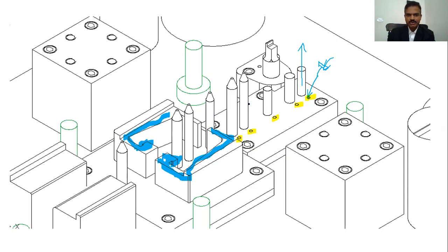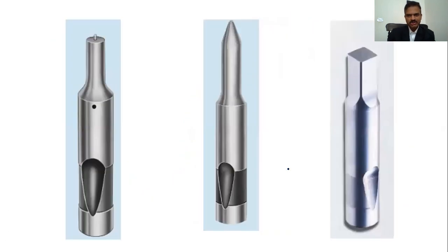So even if it is the pilot, you put a pin in this small hole, push it down, and pull the pilot out. And the same way you just drop it back. It will click into position, and where the ball is going to click is in this teardrop. See that ball, it is a spring-loaded ball, and it's at an angle. So what you do is put a pin through that small hole and push the ball away from the axis of the punch, so this can be pulled out.